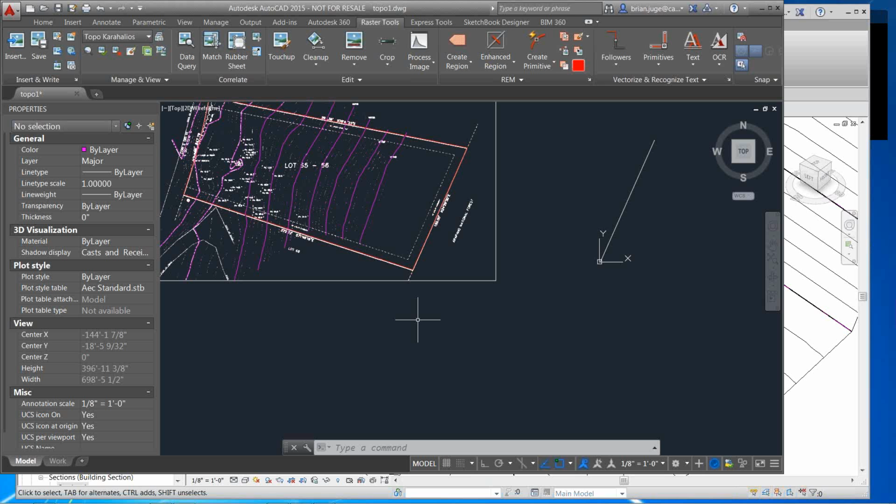And this is kind of where the disconnect comes in, that we have to have a way of logically placing this file in the same place over and over again in AutoCAD so that when we bring it into Revit for origin to origin, it goes to the right location. So what I might suggest would be using the origin command and picking one of the property corners or something like that, so it was consistent.